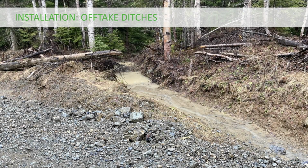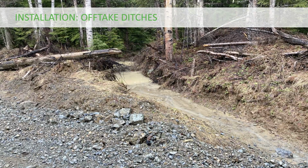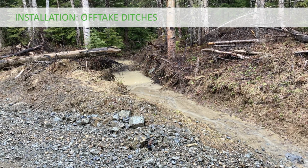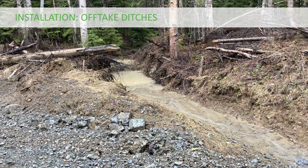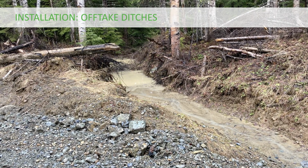The need for adequate water flow away from the road towards the forest floor is essential, but the exact location of an offtake is determined by site-specific topography and cannot always be precisely located in designs or plans. For this reason, best practices and general guidelines are needed for local operators to use their individual discretion.